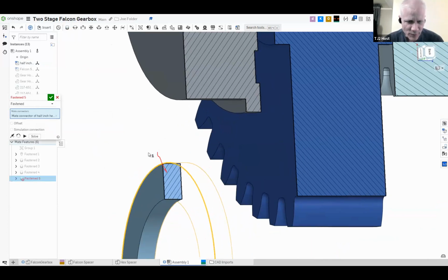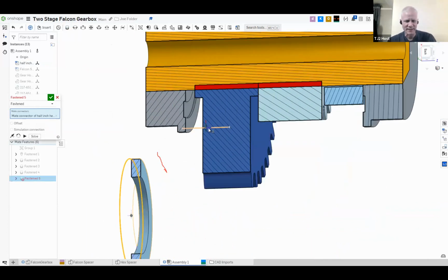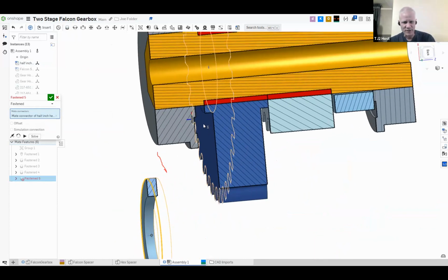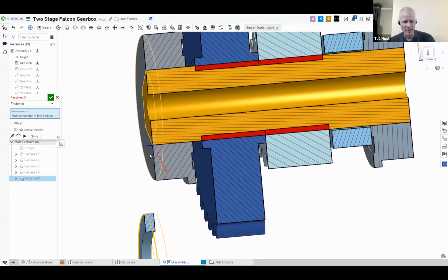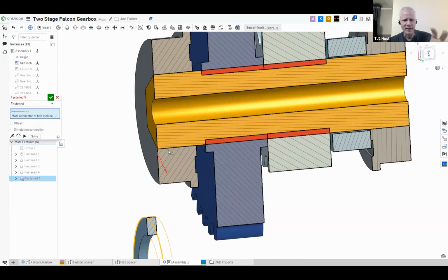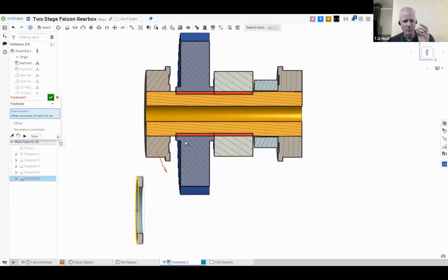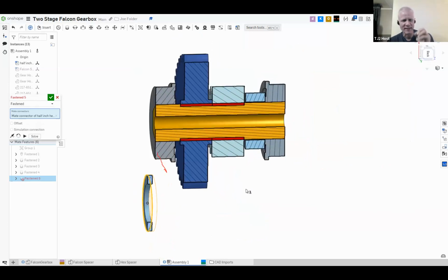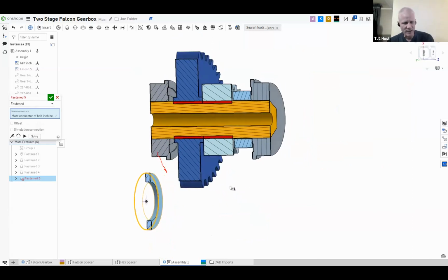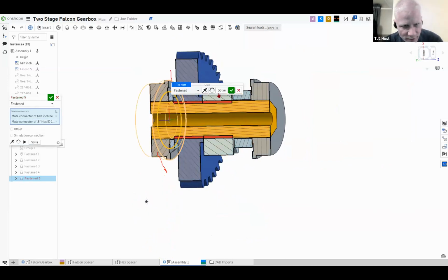Yeah. Do you see the difference? Do you see the difference between selecting the edge and selecting the surface? Do you understand what I mean when I say that? So like the outline of the shape? Yeah. So when you highlight, there's a pre-selection color, and you want the pre-selection to show you that it's selecting the edge, not the face. Because if it's doing the face, it'll show you all the surfaces. So then now you want to check, and you could pick this one up here. Yep, that looks good. So do that.